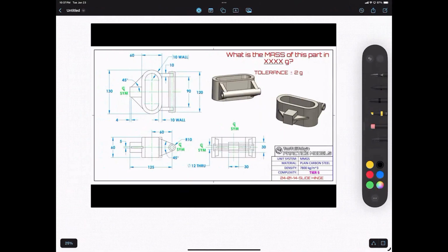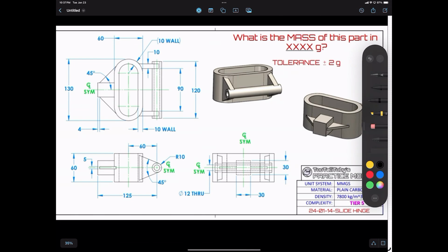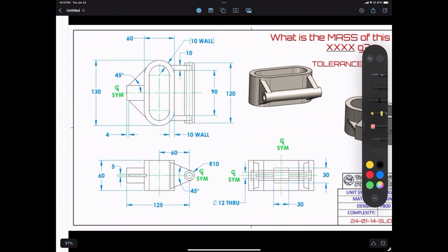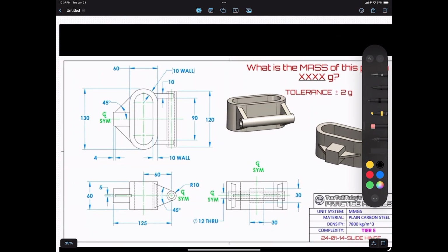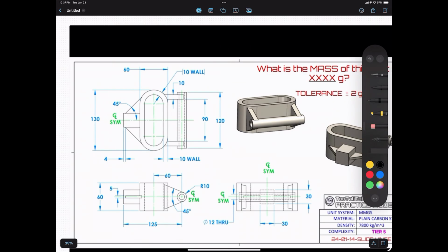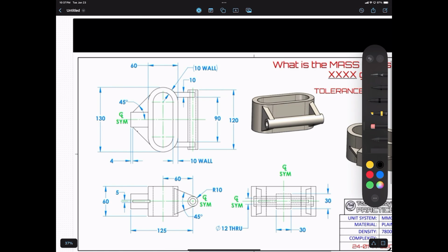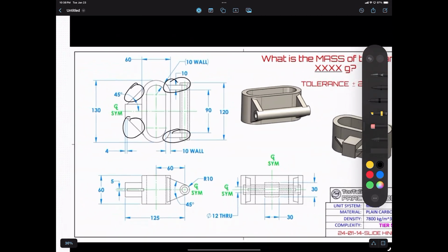Before we begin, let's take a look at the drawing again to see how I looked at this and went about modeling this part. If we look at the diagram, the approach I took is essentially to build this oval shape base first, and then from that build one side and then the other side. There's a lot of symmetry here, it's symmetrical on this side and this side, so there's going to be some mirroring. It's symmetrical over here and here, so there's going to be some mirroring there. So this is a pretty simple part to build.